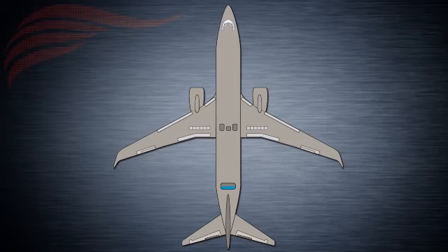Engine start systems rely on bleed air to turn the high-pressure N2 rotor when the engine start switch has been placed in the ground position. Engine and wing anti-ice systems also rely on bleed air to prevent icing formation and buildup, which could lead to rough aerodynamic surfaces and eventually loss of lift. The air conditioning and cabin pressurization systems rely on bleed air to supply and recirculate air through the cabin. All these systems are covered in the engines, ice protection, and air conditioning lessons, respectively.